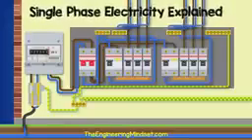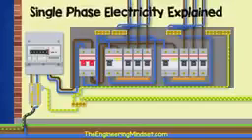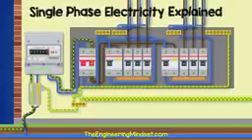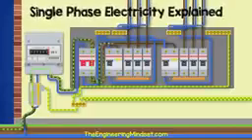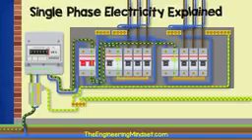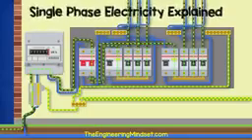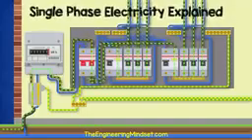So electricity can then flow from the main distribution phase line, up through the service head and the main fuse. It then flows through the electricity meter and into the consumer unit main switch. From the main switch it flows through the RCD, along the busbar and into the MCB. It then flows up around the MCB separated circuits.